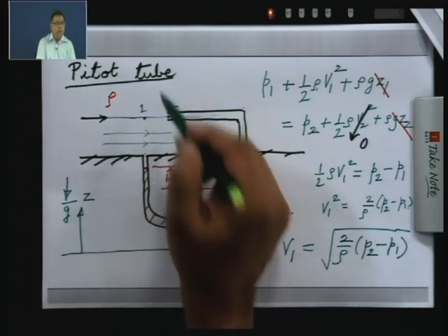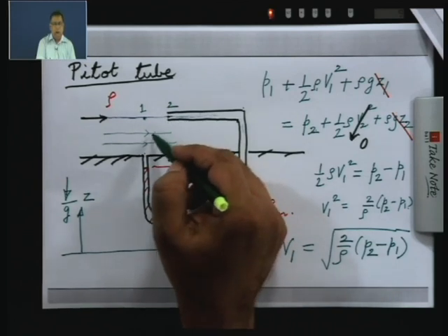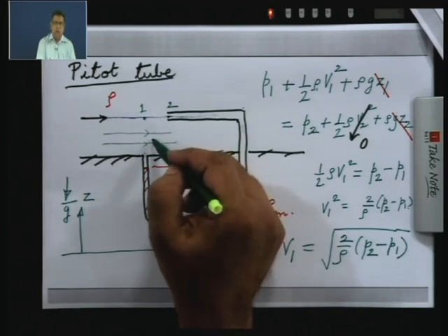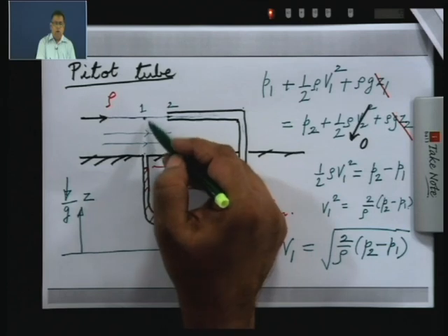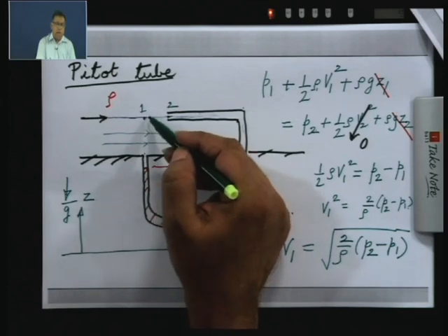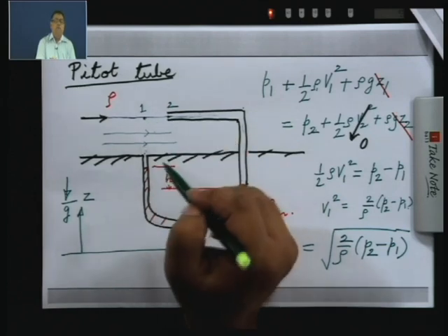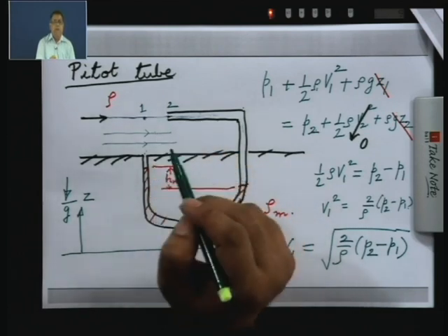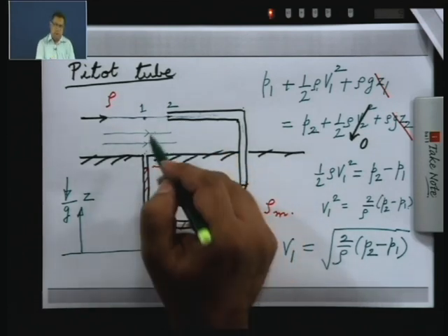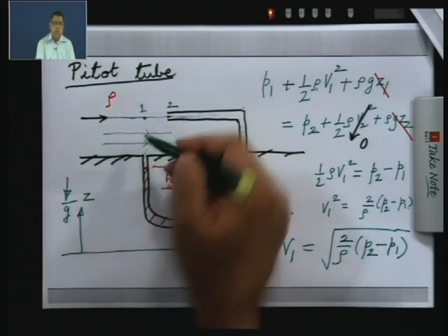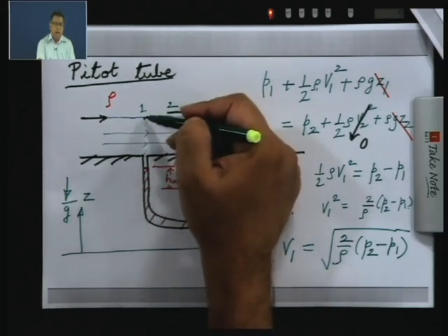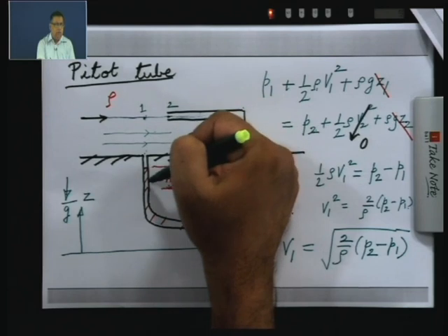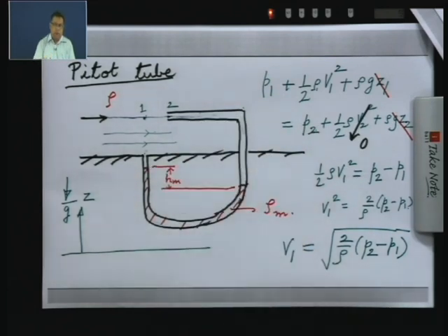So, the radius of curvature is infinite, or in other words the curvature is 0. So, the variation of pressure in the vertical direction, although the fluid is flowing horizontally and not at rest, is still going to be given by your hydrostatic equations. So, the pressure will increase linearly as we move downwards in the vertical direction.